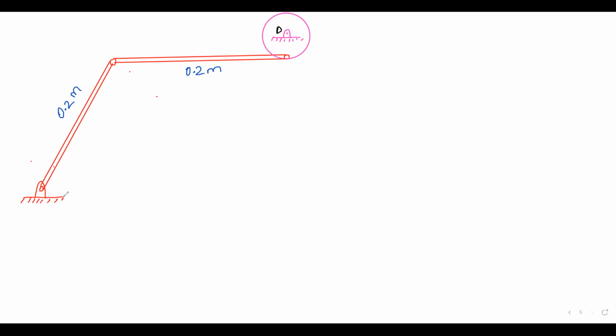Good. So now write the same. Don't proceed to acceleration. Now write VC one more time, VC equal to VB plus, and then equate that. So you will have omega of BC and omega of BC in the same equation as unknowns. So i and j will give you two equations, two unknowns. Good. If you finish this, it will also give me a reference of answers, because again I created this problem. I don't know the answer.